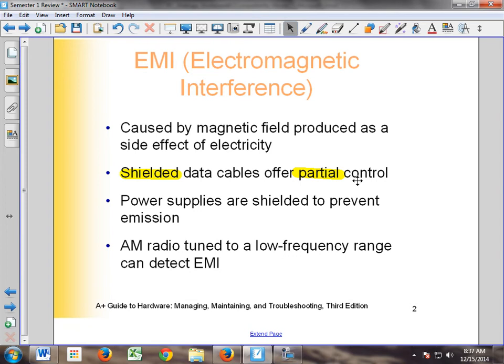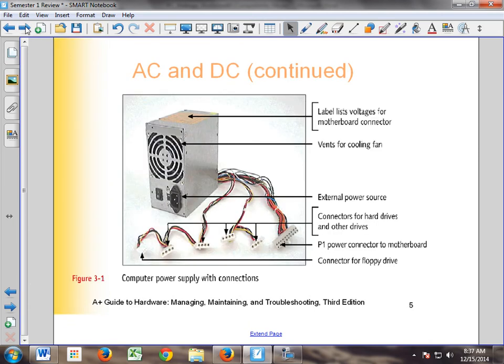In some of the classrooms we were seeing a double image: whatever was being projected, and then behind it a gray image of the same thing. That was because those cables weren't shielded well enough and were causing a distortion. So we're throwing those away and putting up nicer cables as we redo it with the HDMI on this one.